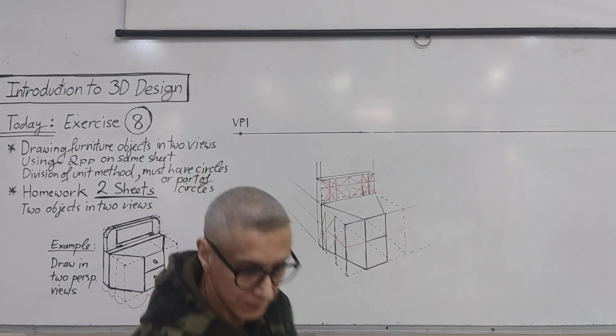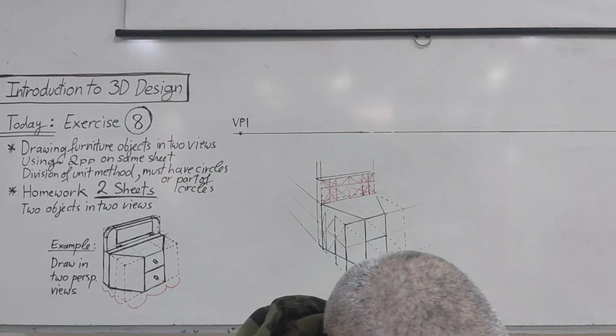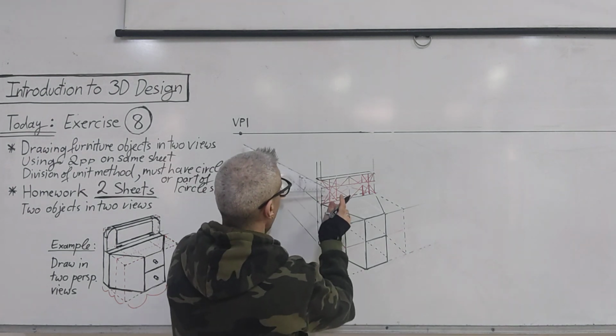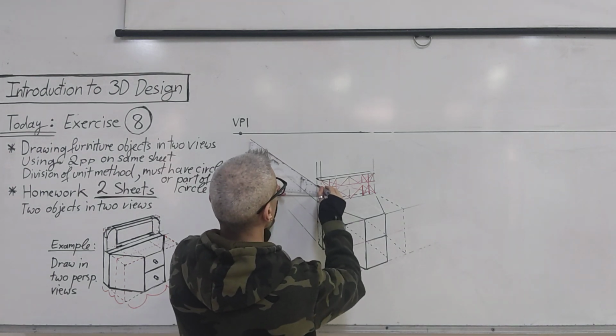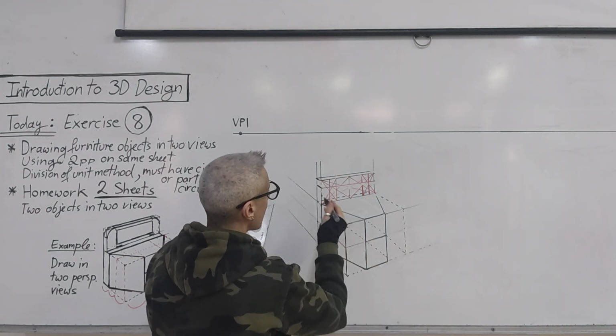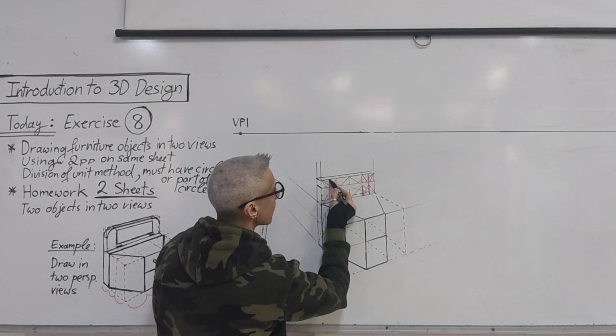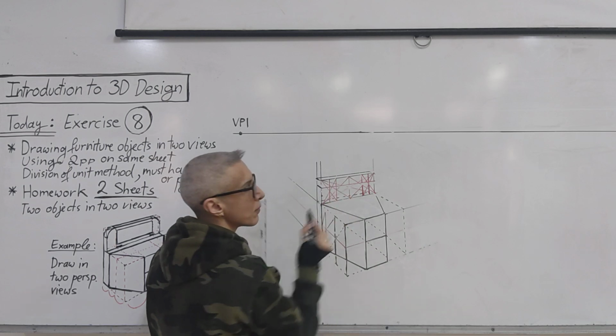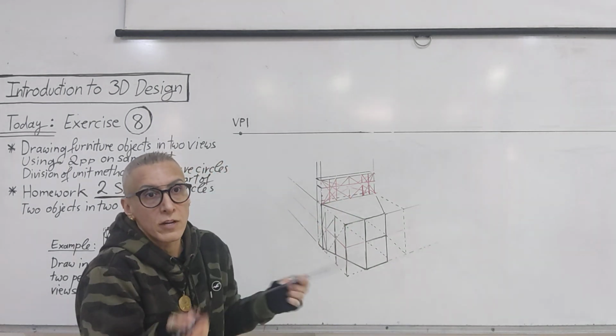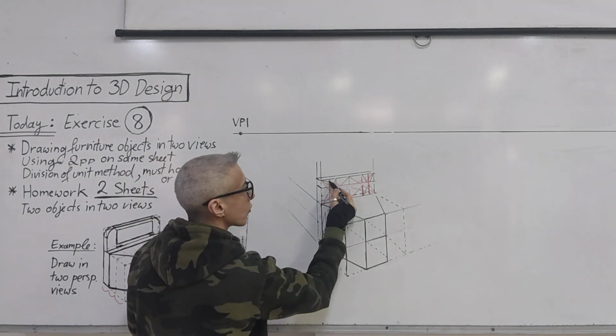From here to the vanishing point. Now, this is what we need. This point and this point, okay? So this is here the square. Remember, how do we draw circles? We need a square. So here is our square, for example.